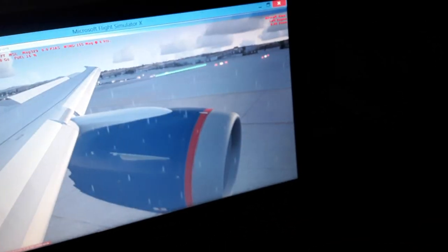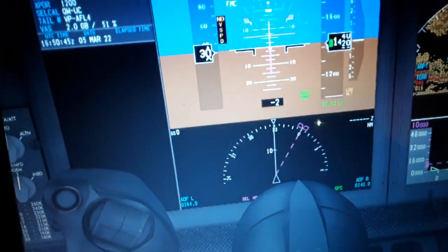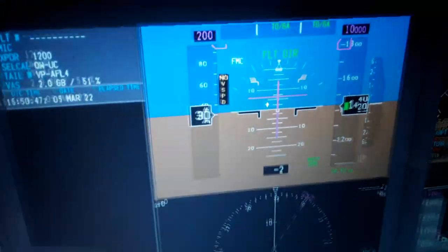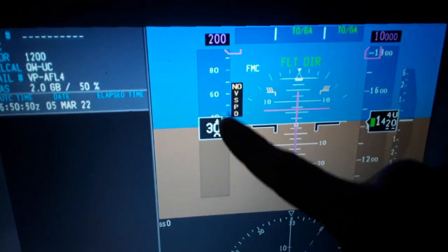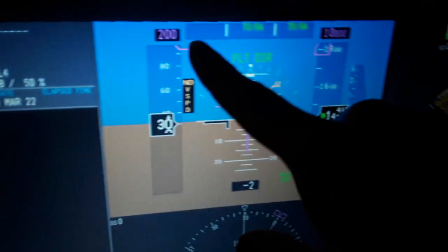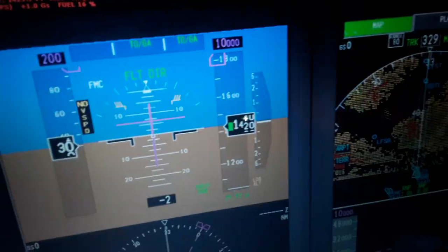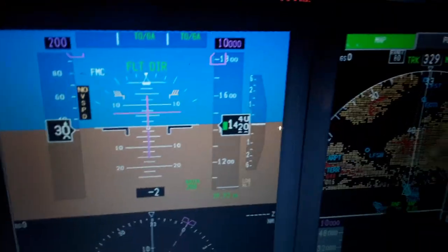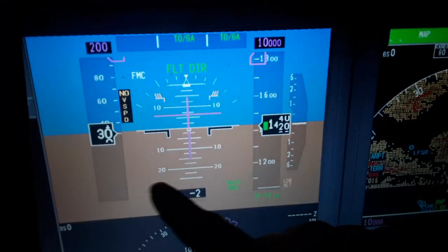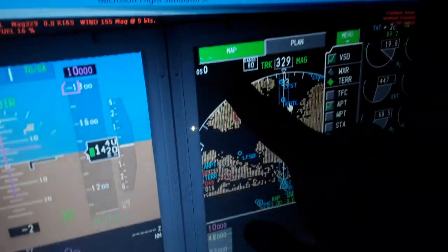I will talk to you in a couple of minutes. So we have the displays first over here. Perhaps first the primary flight display. You can see here the airspeed tape, the indicated airspeed. It increases as we fly. The airspeed selected from the autopilot flight director system panel. Over here the ground speed is displayed in the navigation display, as we see.